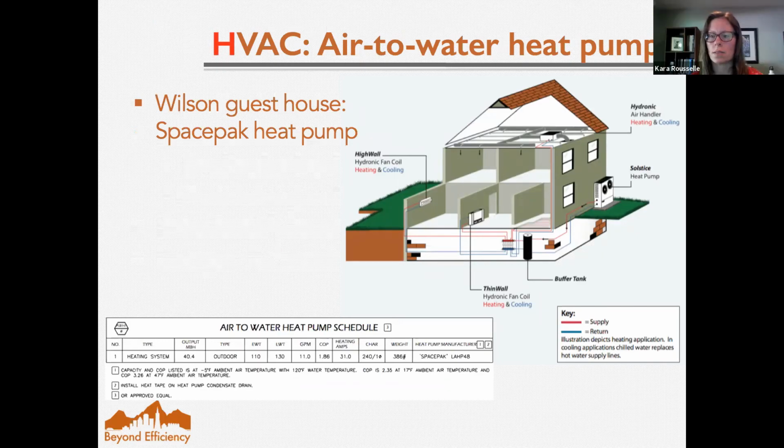So I know on the Sanden, you can use it for smaller areas of radiant floor heating, but you have to be very careful about how it's piped, because the efficiency of the Sanden, a lot of that comes from the stratification in the tank.